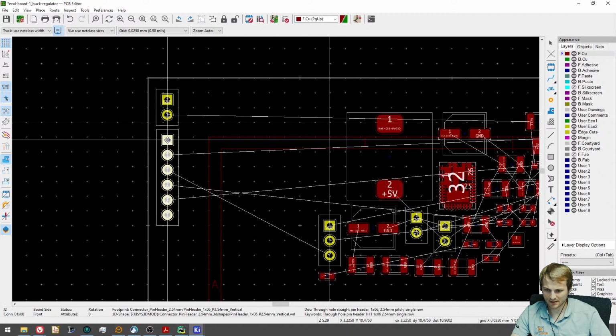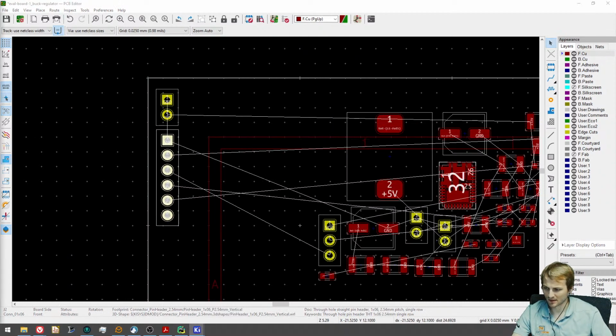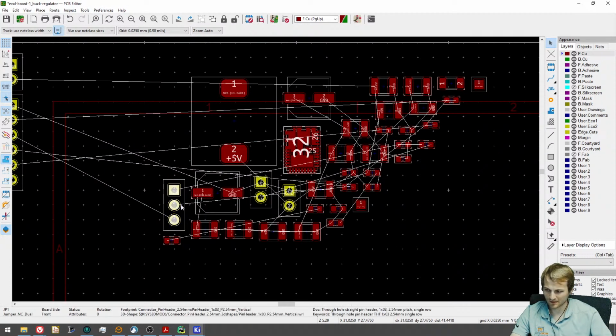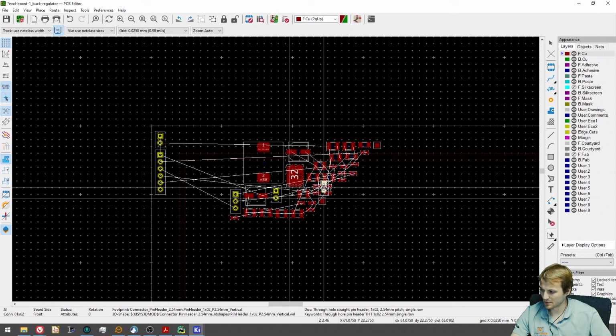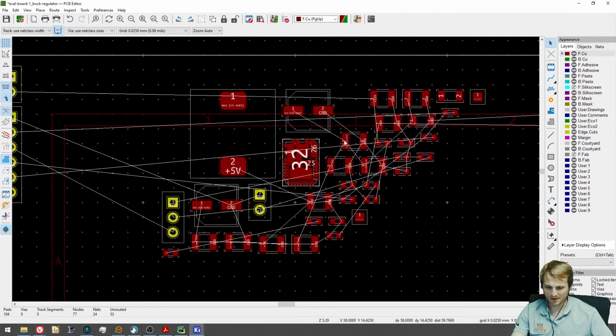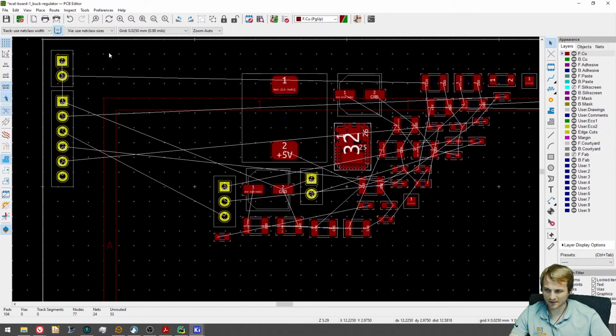Do we then have the connector for the SDA, SCL, power good, all that on that side? Or would we rather have it somewhere else and then our output power is on this side? Anyone have any other thoughts? I think that makes sense, at least to me.